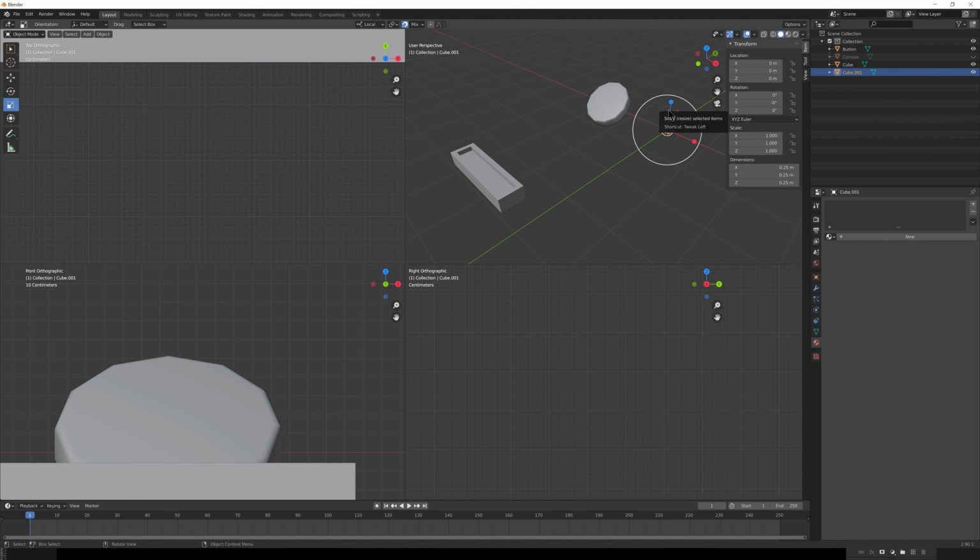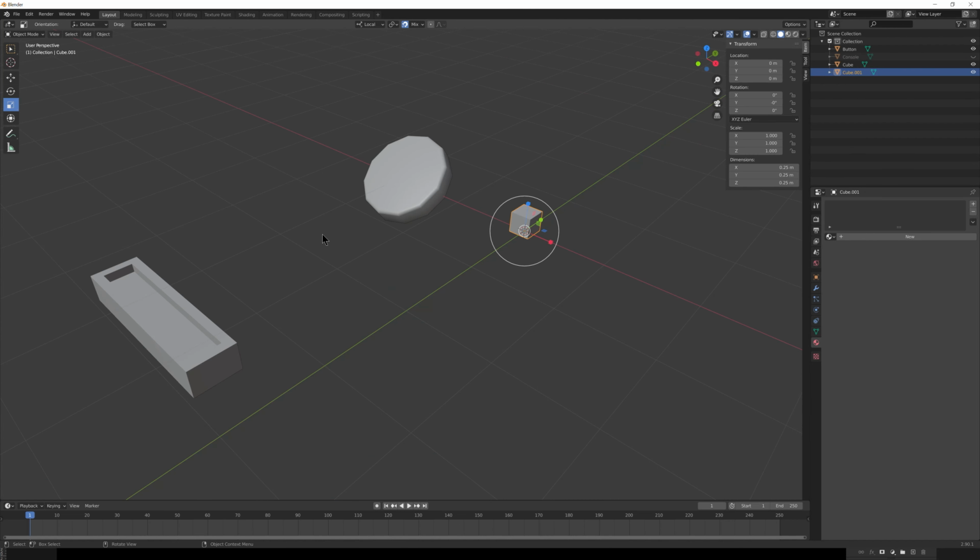So once again, I want to hit Control, Alt, and Q because we don't need that side view to see anything this time. And I can select my object. We can go ahead and hit Shift, Space, and then if we wanted to, we could choose Move, or we can just hit G if we want this arbitrary movement. But you'll notice that our snapping isn't set up correct. So let's hit Escape, come back over to snapping.